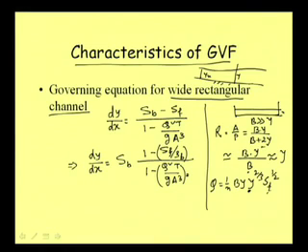Velocity being equal at every section means v square by 2g, the kinetic head, is also equal at every section. And depth of flow being equal means our pressure head is also equal at every section. So the slope of the total energy line and the slope of the bed become equal. That we discussed at the beginning, just to refresh. So in case of uniform flow, our SF, the friction slope or energy slope, is equal to the bed slope. In general, we can write this expression for any depth, and of course here we are making one assumption, that the resistance flow formula is valid. That's why we are writing this equation.